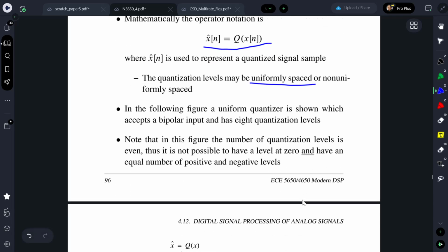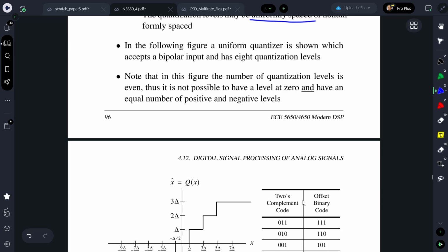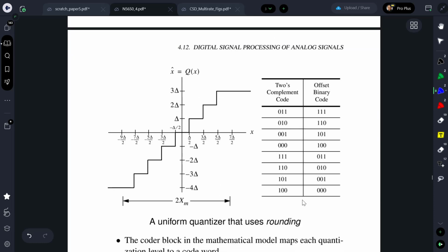So what is the operation of quantization? For signed amplitude values, which is the easiest one to talk about and the one that's most relevant for the modeling we do in this class, we're talking about a rounding quantizer, and that's what this picture is depicting. The fact that you have a stair step at 0 in your quantizer, and then you have a symmetrical set of stair steps on either side,